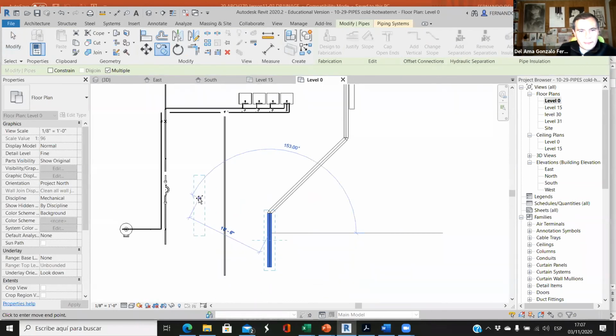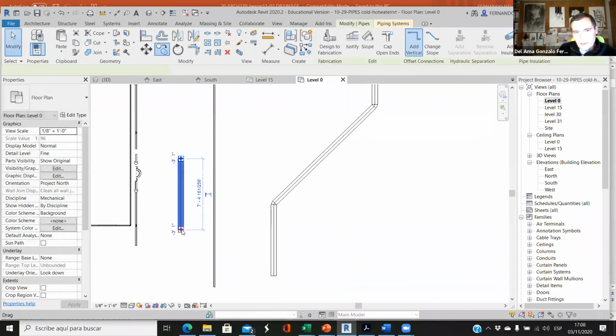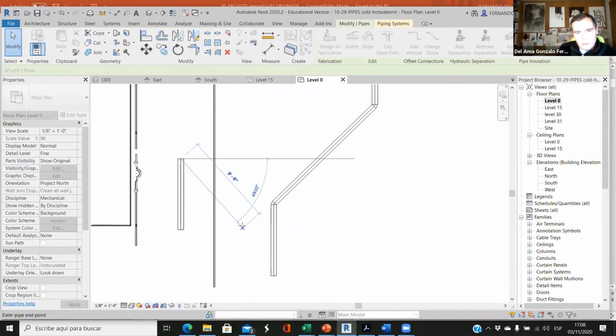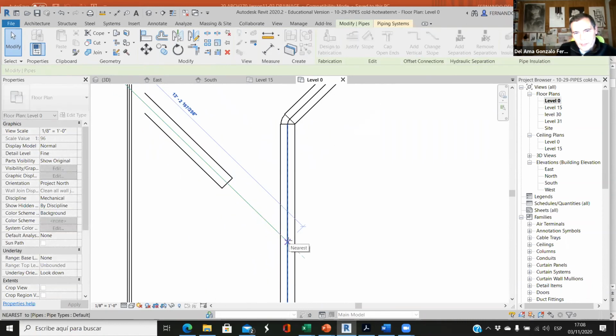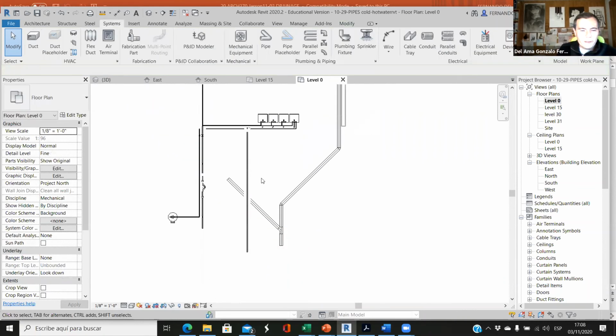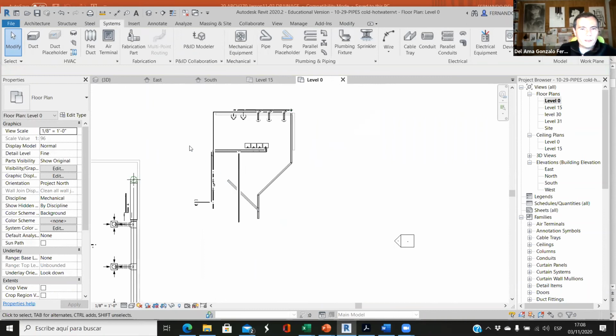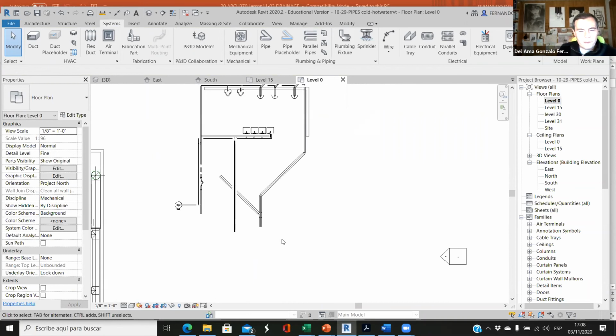if there's another toilet, and at the end we have to connect all the toilets to the same system. So make sure that every time we connect to horizontal pipes, we also have these 45s. Okay, so if this is coming from the ladies' toilet, that would be somewhere. So this is the men's toilet. The ladies' toilet will be here. So there will be another vertical stack, and then in the horizontal, we will connect this way.